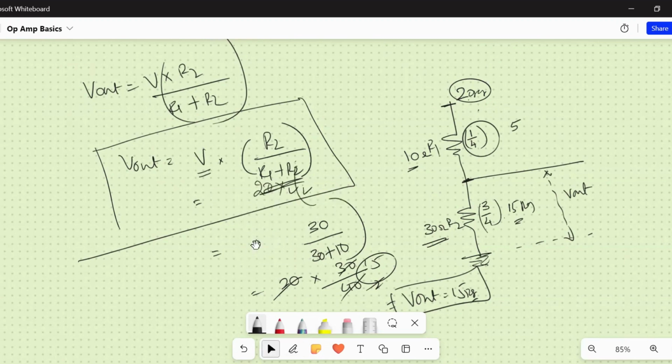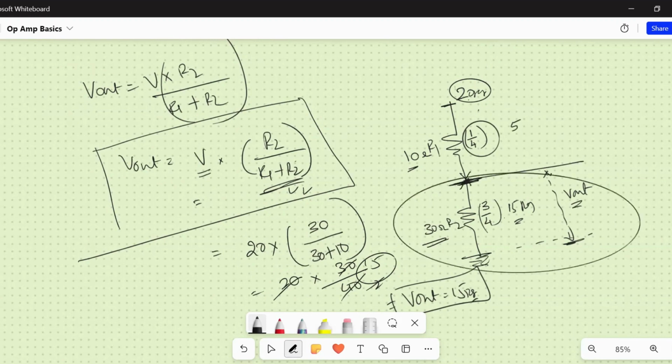It is pretty simple. Wherever you want to take the voltage output, this is the voltage, this is the area where you're trying to divide the line of voltage. So this is the voltage with respect to the ground. If you take V out, this portion is coming from the main voltage, that is V. This is the main voltage V. And here a portion of this main voltage is dropping. The portion of the main voltage dropping is based on the ratio of the resistors that we use.